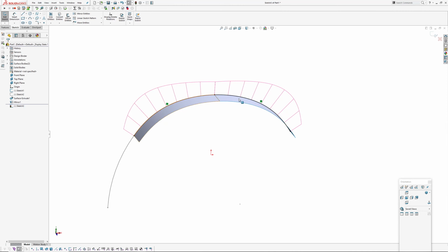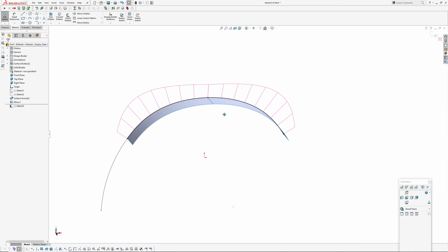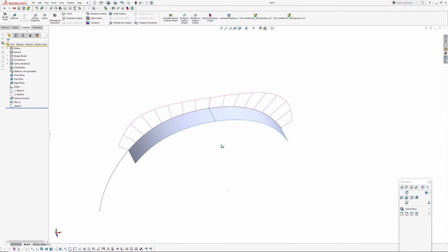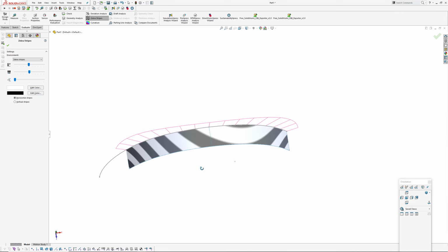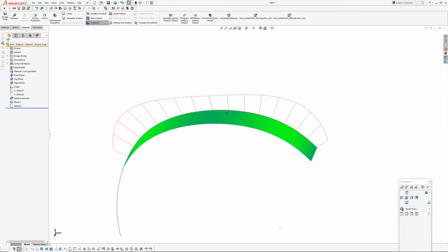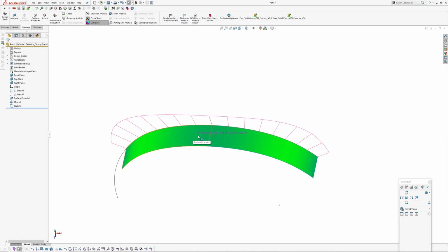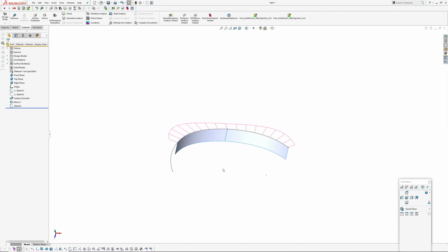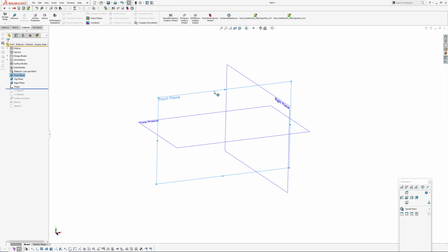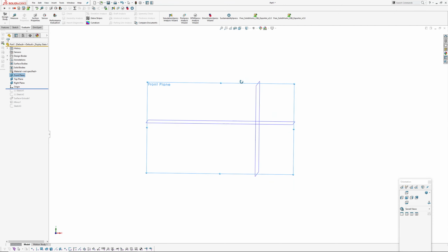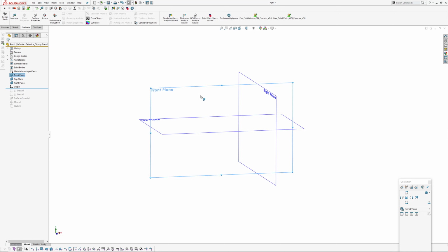And I mean, you can tweak the geometry there, like there is a peak in the graph there. It is curvature continuous because the graph isn't stepping. If it was stepping, that means it would be tangent. Yeah, so you can get a bit smoother. I mean, on the curvature plot, the curvature is the same because it's matching. So conic's great if you're going to go like a full corner, you know what I mean? So rather than flat corner flat, you're just going to go right through like a full corner.